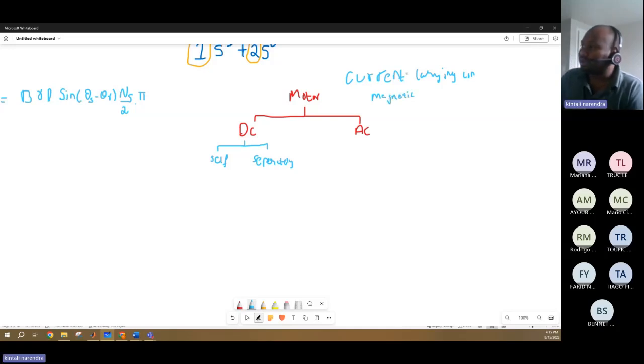Okay, so a current carrying conductor is very simple, a piece of coil which carries current. Now the magnetic field can be either a permanent magnet or an electromagnet. Again, if you want to use an electromagnet, you need a power supply. So for developing the magnetic field and for the conductor, if I use the same power supply, then it is called a self-excited DC motor.